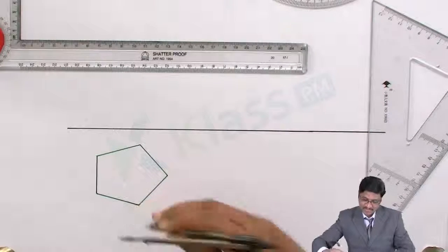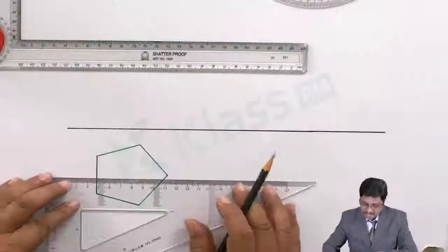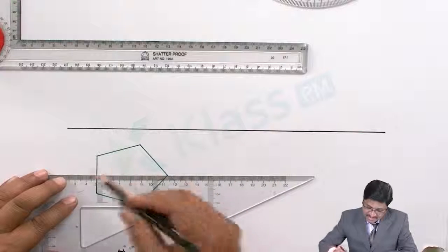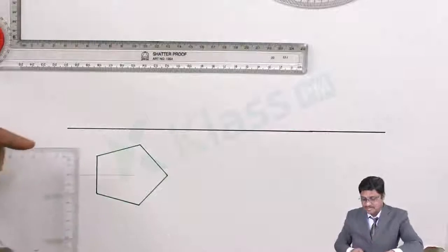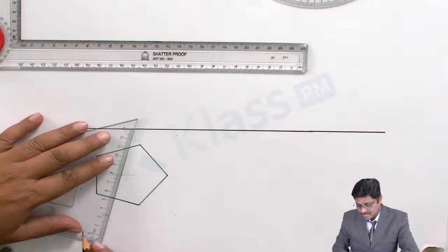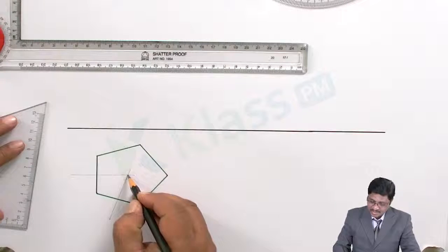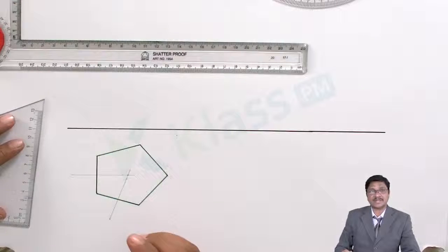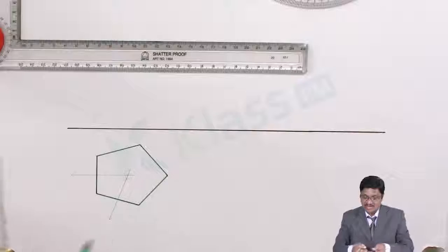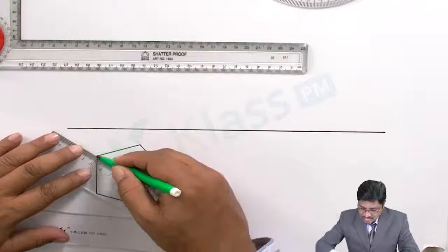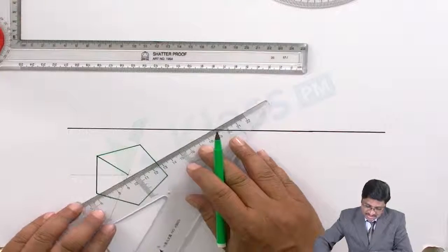Once located, connect and extend the perpendicular bisector points so that they intersect somewhere. I draw the first perpendicular bisector, then the second, and extend them both. Where they meet will be the center of the polygon. Now connect every base corner with the apex, which appears as a slant edge.